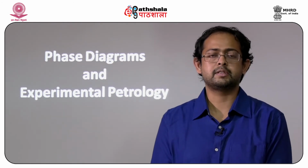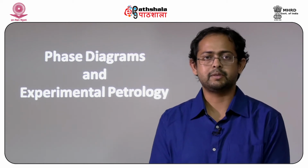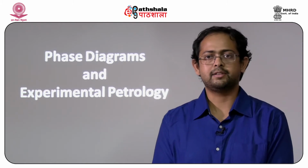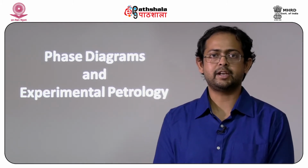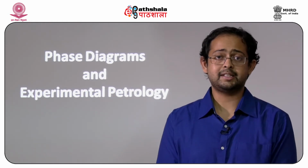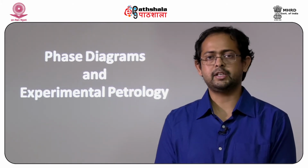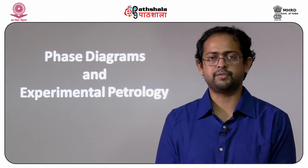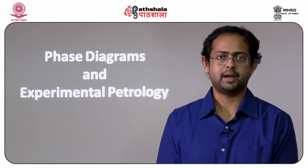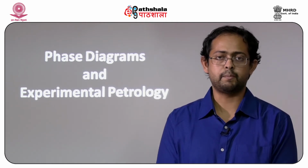Say for example, in a system of forsterite and silica. What is the formula for forsterite? It is basically a magnesium silicate, correct? So, it is Mg2SiO4, and silica is SiO2. So, out here how do we define components? As I said, it is Mg2SiO4 and SiO2. Remember, as you can see from the formula, it is actually made up of magnesium, silicon and oxygen, but that is not the way we define constituents, components.